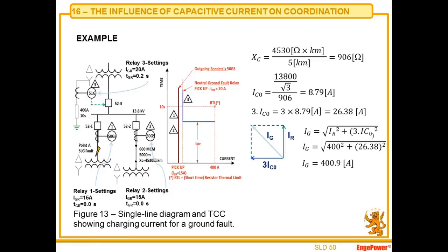I am very upset because in most of these studies I read, people set this relay here as much as 75 amps, 100 amps. The guy doesn't know this specific issue. So 20 amps. What happened here? What happened here was the following. A ground fault happened here.